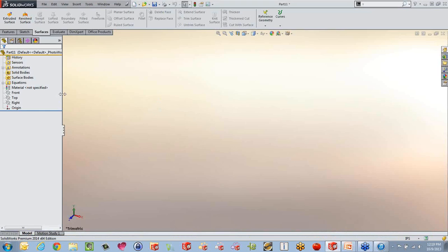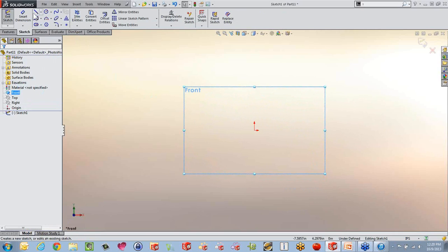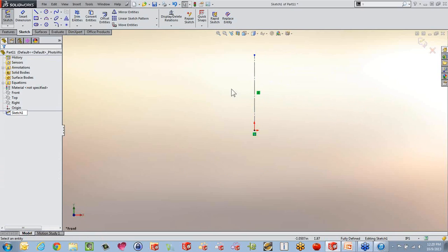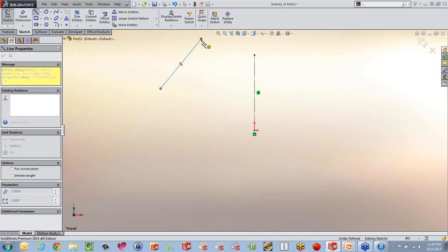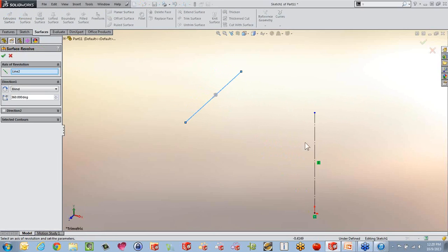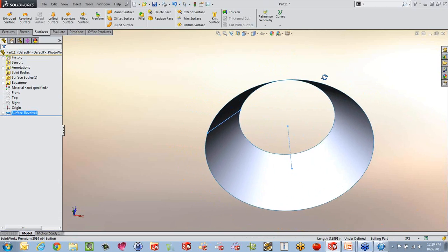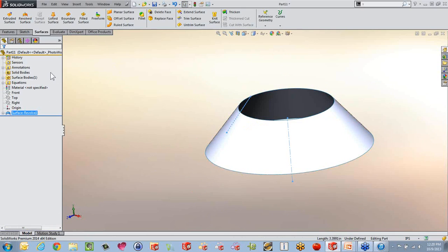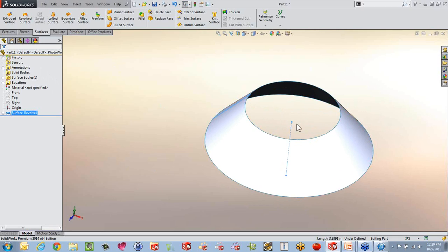So let's get back into the SOLIDWORKS and into document. So we got the extrude. I showed that one before. We also got revolve. Now revolve works pretty much just like it does in SOLIDWORKS. So if I open up a template here on the front here and I just sketch a line straight up here, make a construction, then I could sketch another line, an angle, and if I went into my surfacing toolbar and did revolve, well, then I would get a lampshade, right? And again, we could do this in SolidWorks. We could do that with a standard revolve, but just to show you, it works the same way.